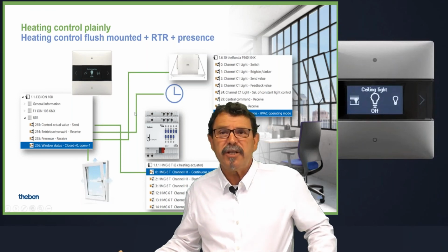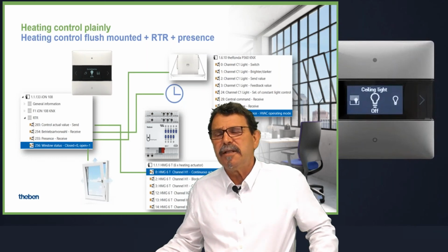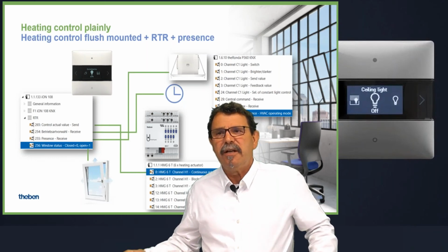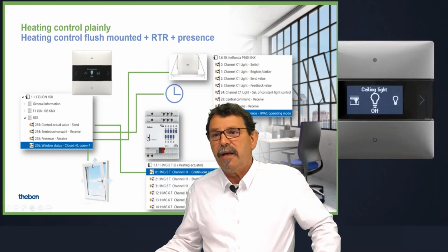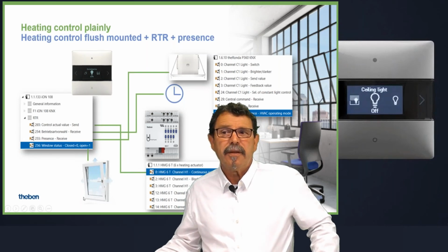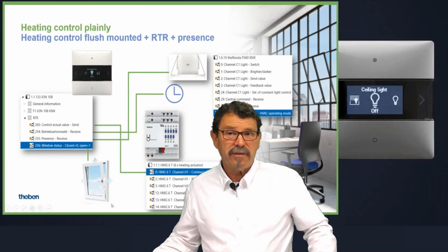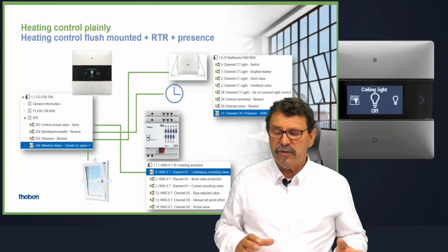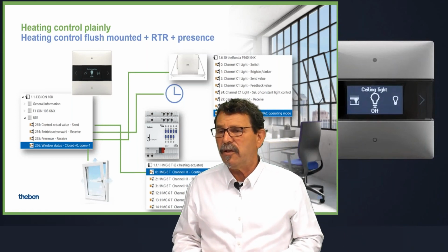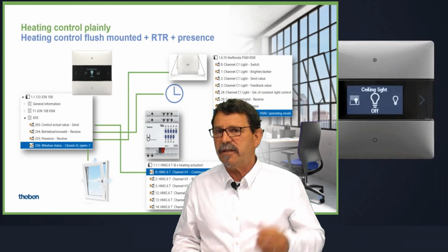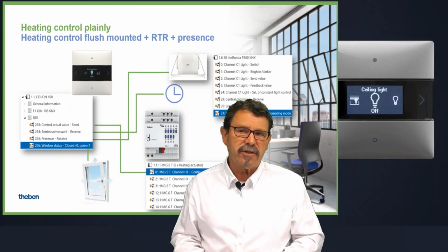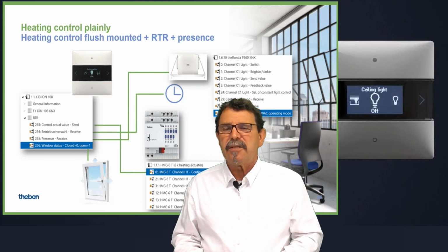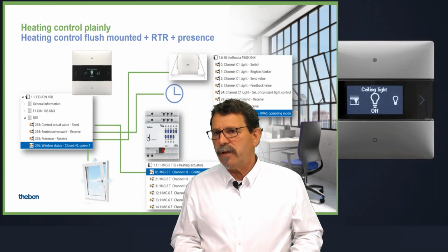Just a few communication objects are required to bring this comfortable control for office buildings, schoolrooms or whatever in control. As well, don't forget, we talk about energy savings at all. Nevertheless, if you talk about heating control or cooling control, if there is an option, if we have the event of opening a window, or opening a door to a balcony or to a terrace in our office, then we can stop the heating or the cooling accordingly.